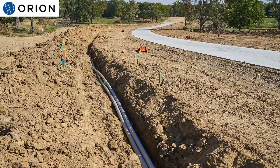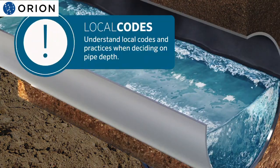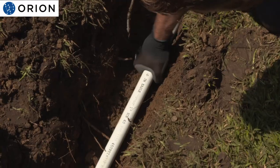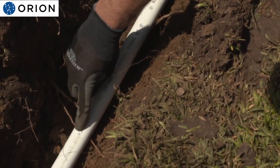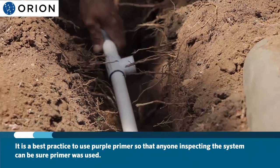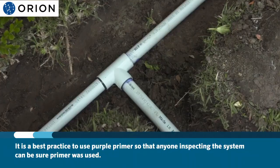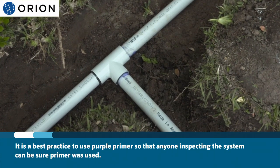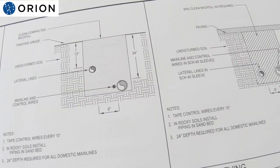These suggested depth numbers are based upon many variables, including job location, weather, and other types of elements. Please check your local codes to determine what the minimum expectations are in your area. When laying the pipe in an open trench, be sure to install the pipe with the wire facing directly up. Getting in the habit of installing the pipe this way will make it easier when the inspector comes to check the installation of your irrigation system.